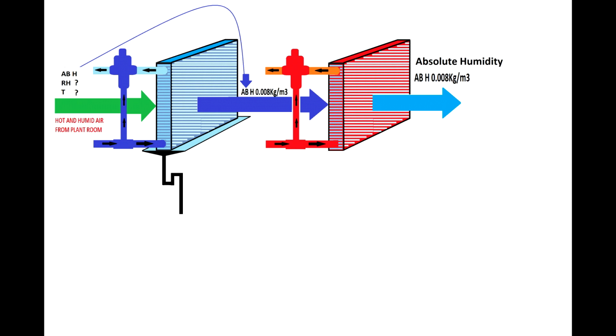So it is very important to have an appropriate calibration so we control the airflow and do not exceed the maximum quantity of air that can pass through a heat exchanger as per its specification.